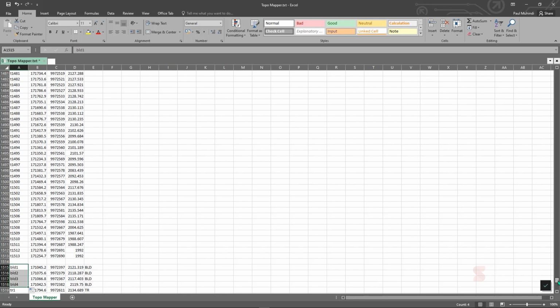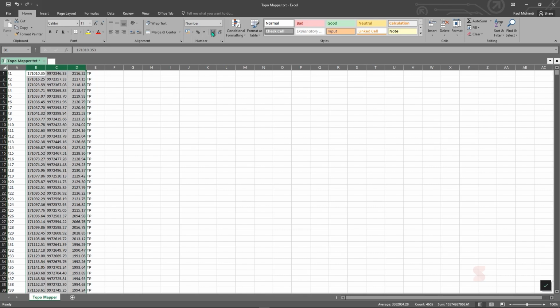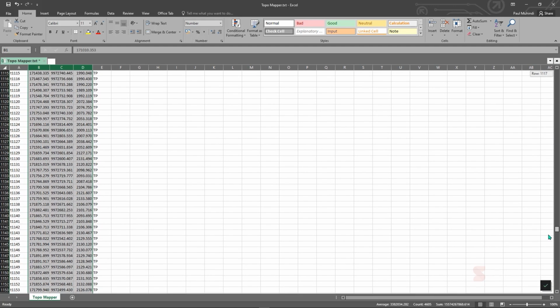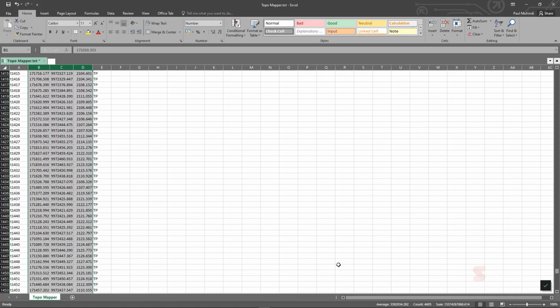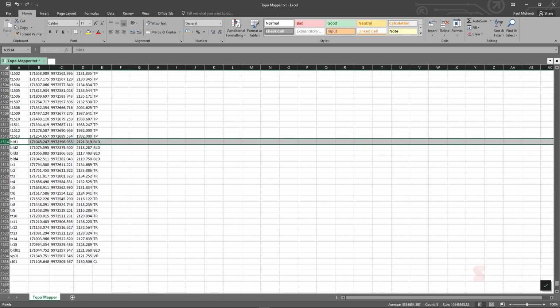Then I'm going to go all the way up so that I can extrapolate these TP points like so. Then we're going to just increase our decimal places to match. So just do like this. Use this icon here. So we have reached the third decimal place, and we also did the setting in Global Mapper. So only one row is remaining to be deleted, which is this one. Right click, click on delete. And that's how we do it.